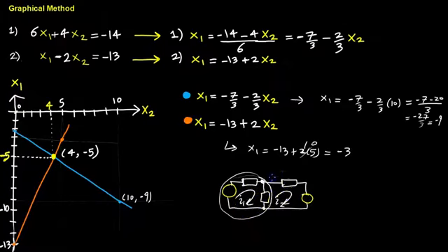In the second loop, you would say the same thing. You would go up and say, okay, sum this voltage rise or drop, sum this and sum this, and set that equal to zero. And with your two different variables, I1 and I2, your goal would be to find the set of values for these two variables, I1 and I2, such that the system is balanced, so that the system is satisfied. In other words, you want to find a current where these systems connect correctly, and you have the correct voltages and currents through and across each element.